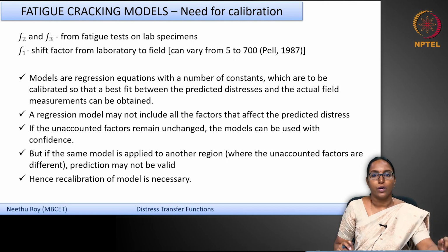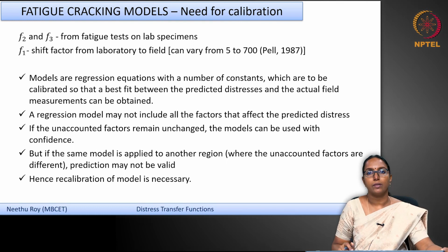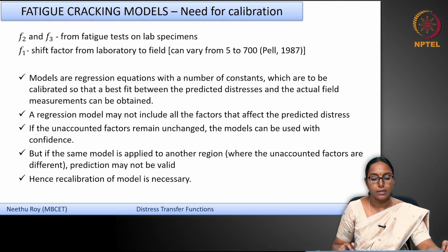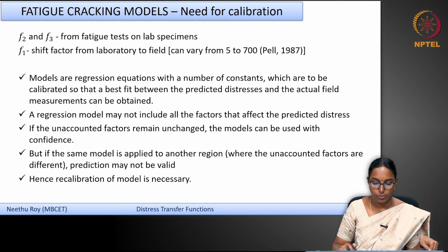Okay, so moving on, I just wanted to reinforce the aspect that there is a need for calibration when you want to use these fatigue cracking models, unless they have been developed based on extensive data applicable to the particular field condition where you are going to use them. The models are regression equations with a number of constants, which are to be calibrated so that a best fit between the predicted distresses and the actual field values can be obtained.